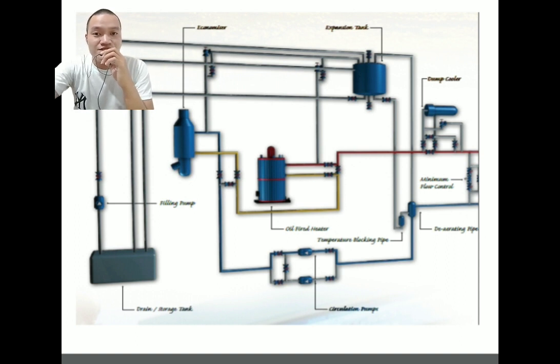The reason for this is to make sure that when the pump gets turned off, the residual heat in the various components of the system does not thermally crack the heat transfer fluid because it can affect it.